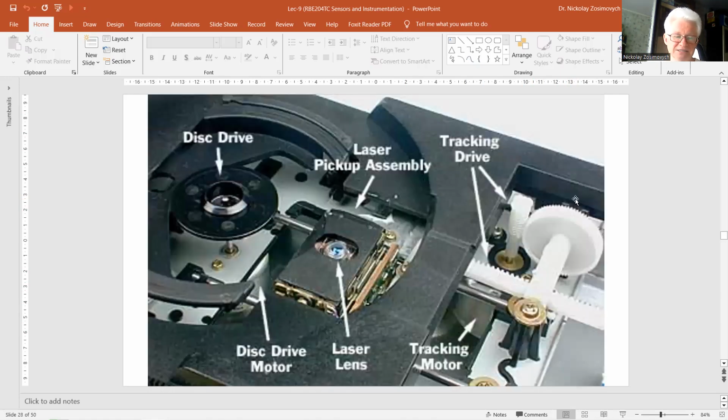Compensation, balancing, and feedback make the output more tolerant to changes in the path. Instead of a single receiver, a pair or a quad, meaning four tiles arranged in a 2x2 matrix, is used. The position of the incident light beam is controlled in such a way that all sensors have the same output.